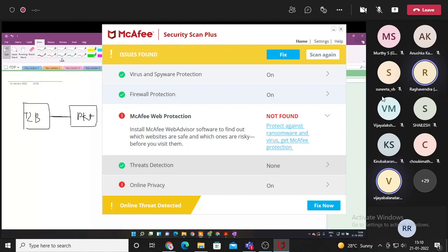The line coding scheme that we are using over here is Manchester, and there is a reason behind this. Let's say instead of Manchester, I just do normal on-off keying. By on-off, let's just say a return to 0, meaning if it's a 1, it will stay over here, and if it's a 0, it will go back.